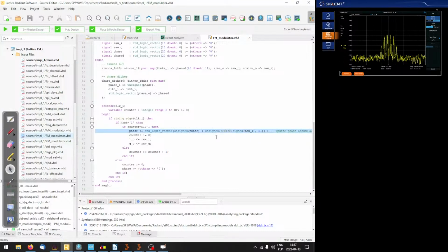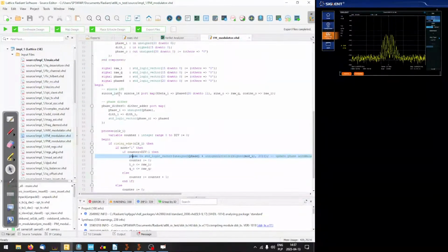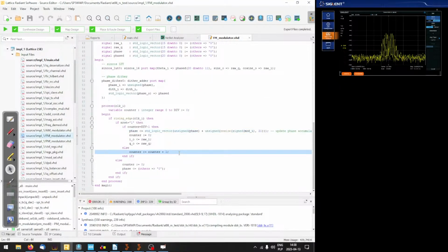Then we are going to use this phase to get a value for the sine from a lookup table. Yeah, okay. So the tuning word is going to be 16 bits, I believe, signed, but in our case, we actually don't need the sign because CTCSS codes are just sine waves, and we don't care if that's a positive or negative frequency, so we don't care about the phase.